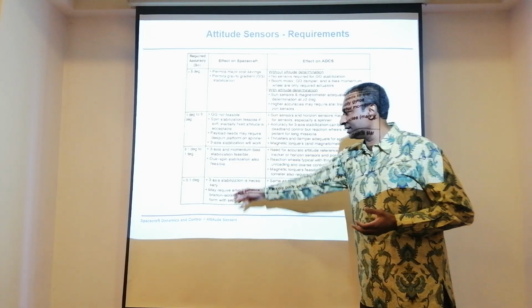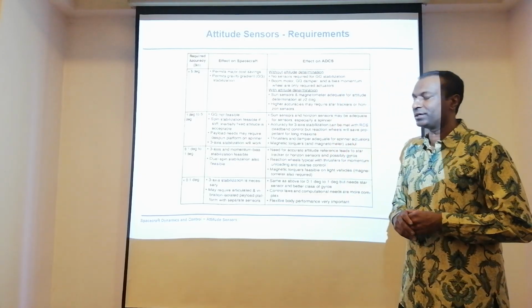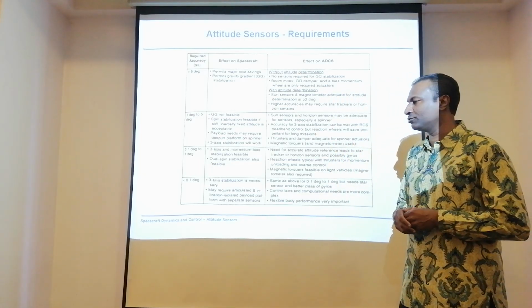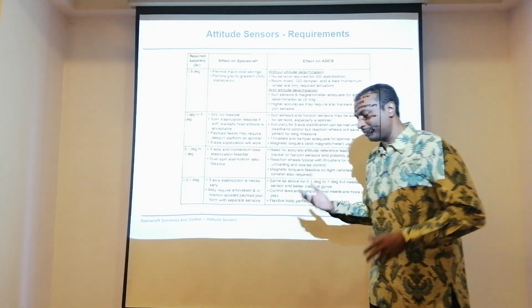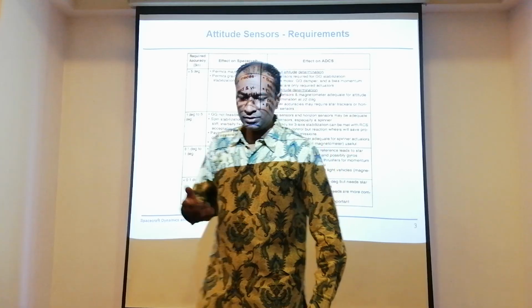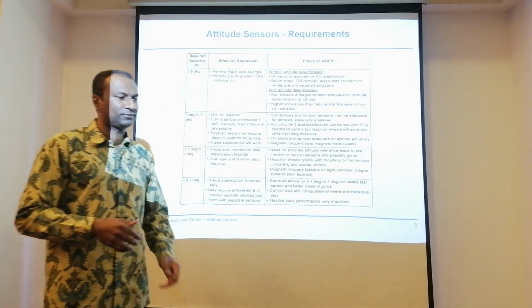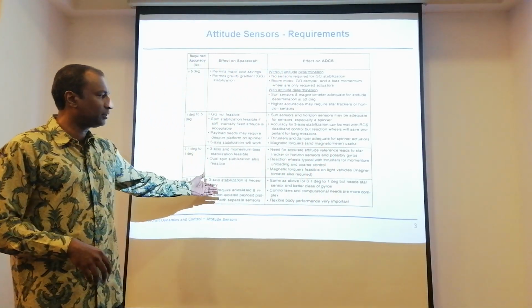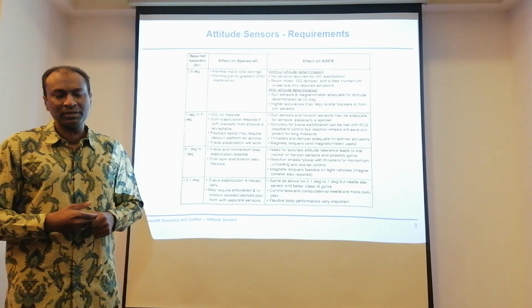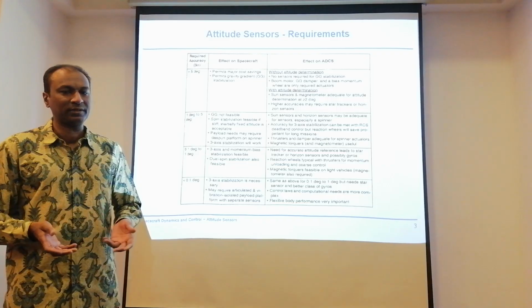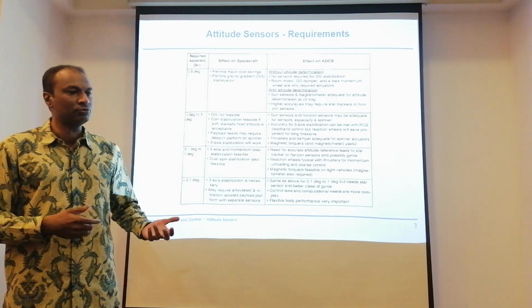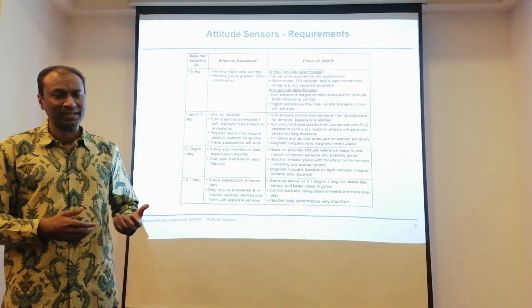Now, for the typical, or rather good quality satellites, we must have good quality measurements. Assume that it's 0.1 degree or better. It could even be 0.001 degrees of attitude accuracy. Then we are looking at options like the gyroscope. That is mandatory. If you have those classes of sensors, obviously you will have good, solid actuators as well.